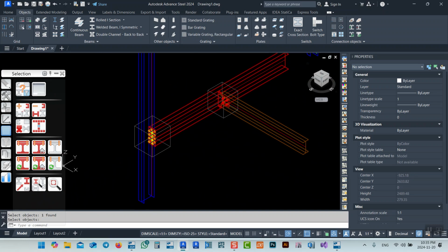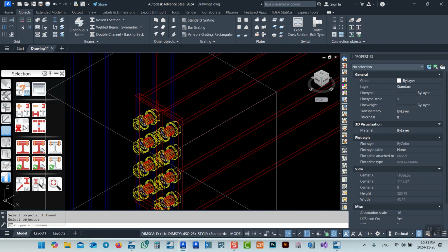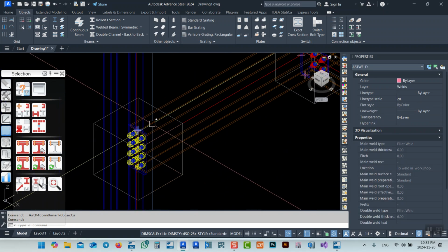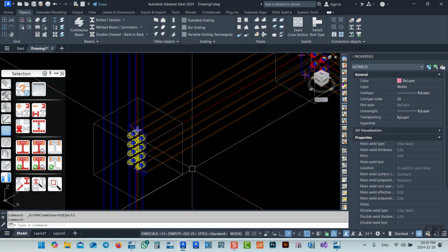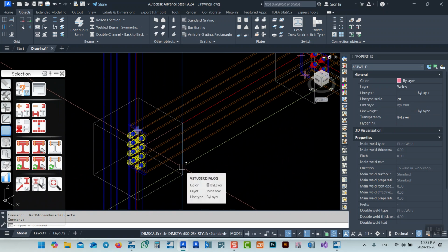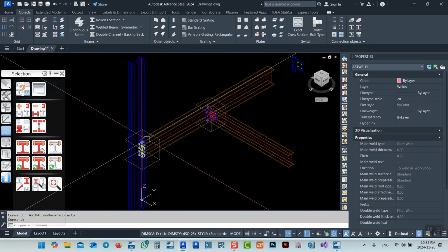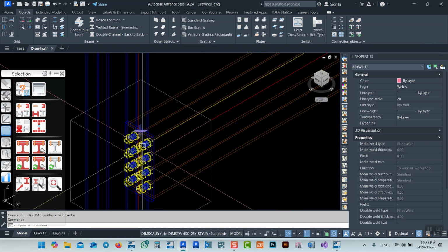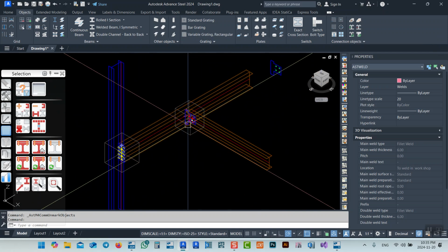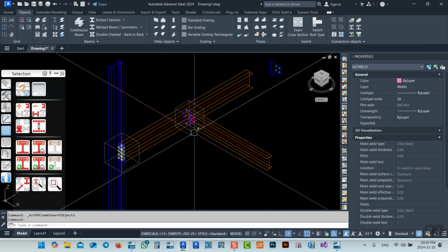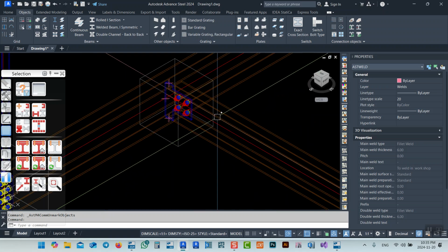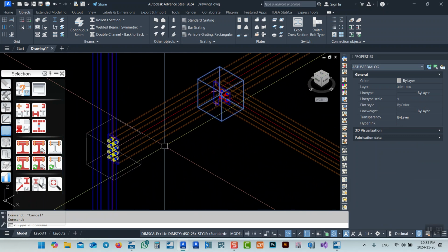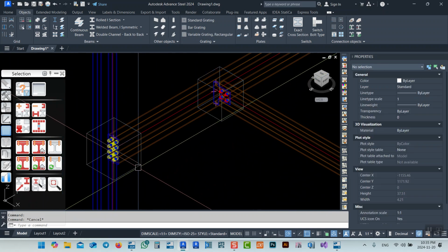This one, look, when I try to select one of the weldings that has join boxes, which is the connection template, now I cannot add any kind of connection to this. I cannot add any kind of plates for this one, because it's not in the standard connection. But if I delete the join box, for example for this one, let's try this one, no problem.